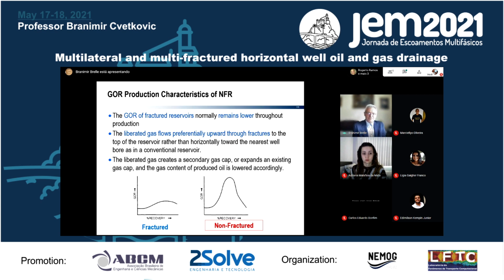That means you will get a huge production of gas in the well, but looking at the whole system, GOR will be lower. At the well, the system will be producing a lot of gas because the network is like a multilateral well producing gas to the producing well, and then the gas oil ratio is lower than what should be normal.